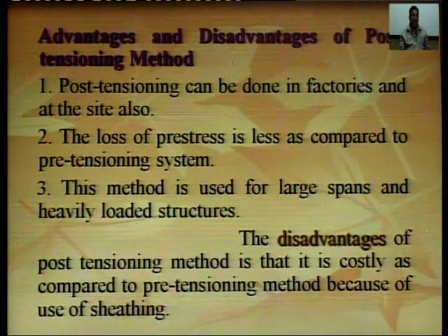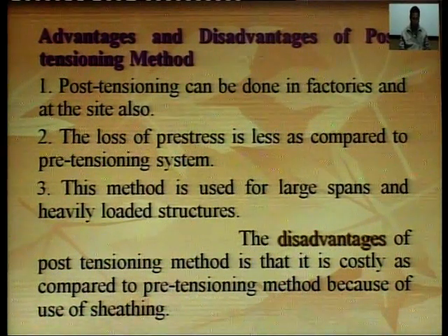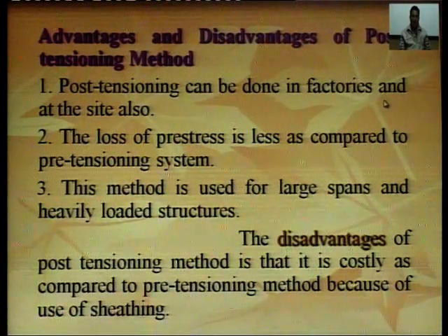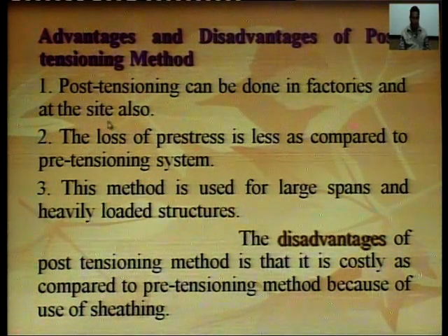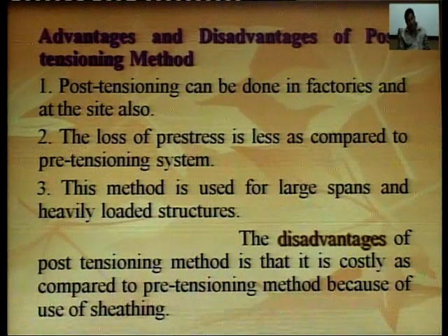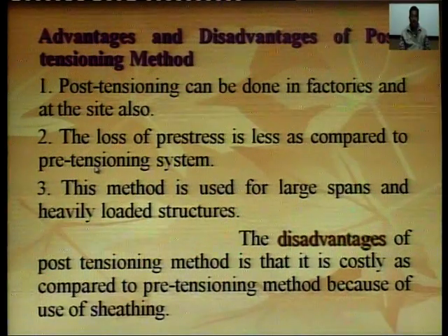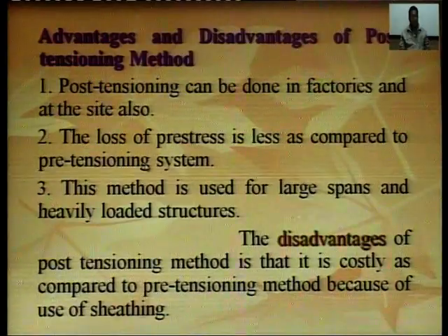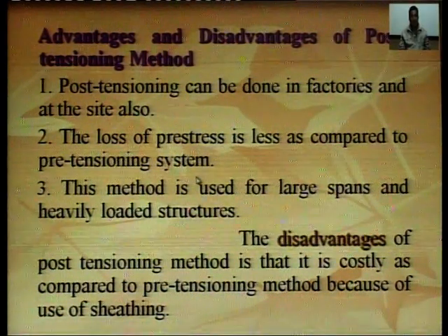Next, the advantages and disadvantages of the post-tensioning method. Post-tensioning can be done in a factory and at the site also. So, this method is suitable for factory as well as site. The loss of pre-stress is less as compared to the pre-tensioning method.